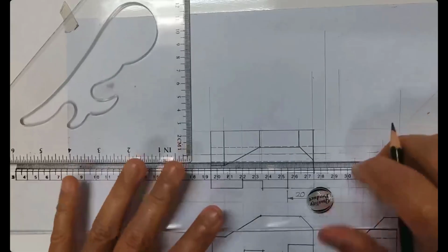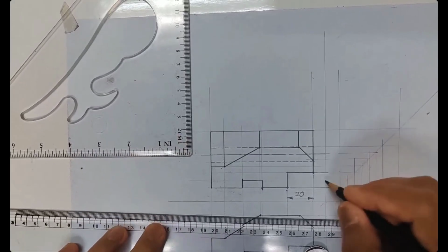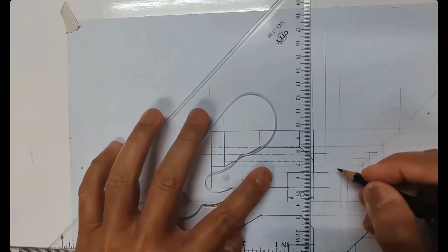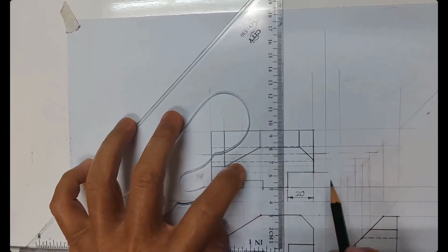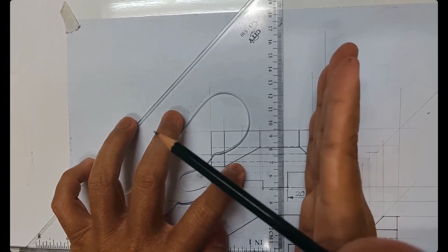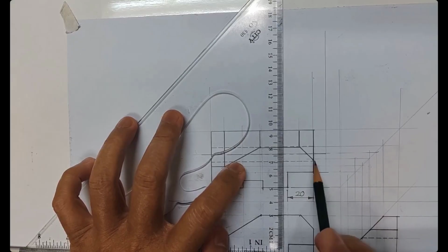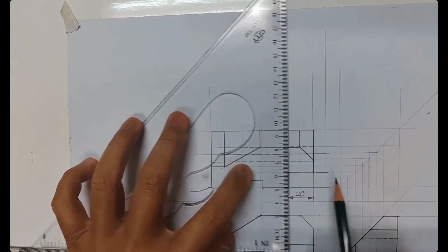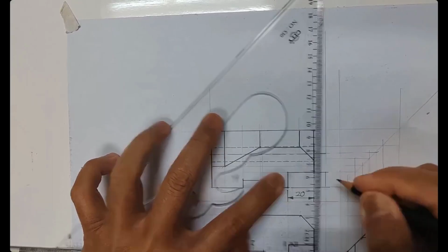Okay, this one here I already make the extension line, so this is the extension line. This one will be, I'm using 3 for dimension. Okay, because this is the most right edge of your object, not too close. 2 letter height, what, 6 millimeter from this vertical edge. 6 millimeter, so about this position, so this will be your dimension line.